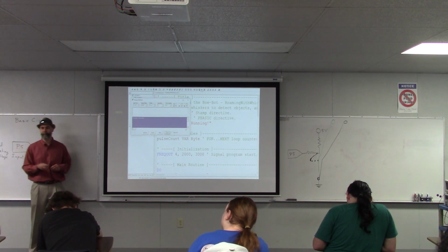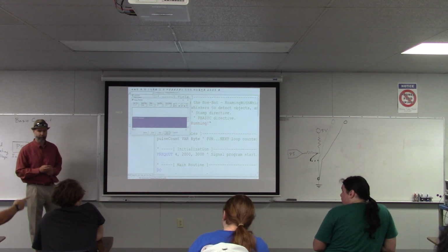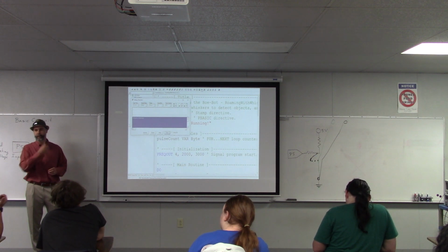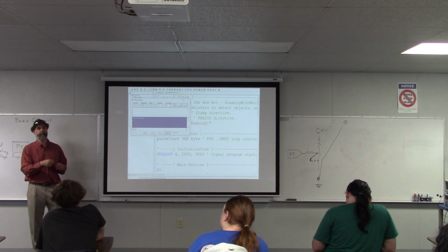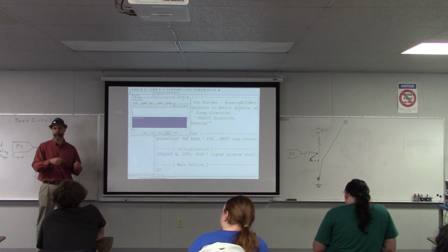Yeah, instead of the 220 resistor, could you have a diode there instead? So that if the P5 was for output, it just wouldn't go to the rest of the circuit? Yeah, that's a good point. You could put a diode there facing towards the pin, right? And then that would...